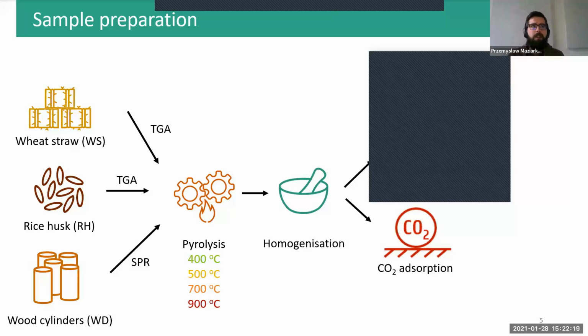that low value indicates that there is not a lot of porous structure inside the material that is assessed. That means that most of the specific surface area assessed by the nitrogen is located on the surface, because adsorption takes place on the surface of the material as well as inside the material if there is porous structure.